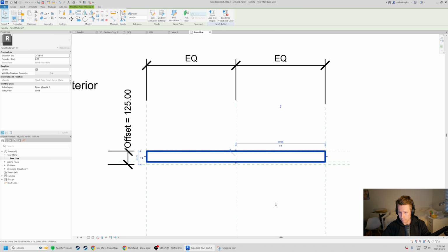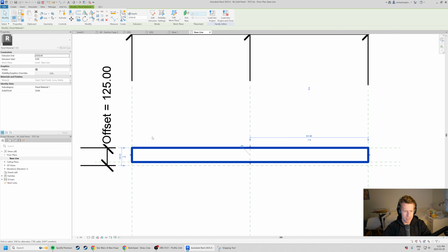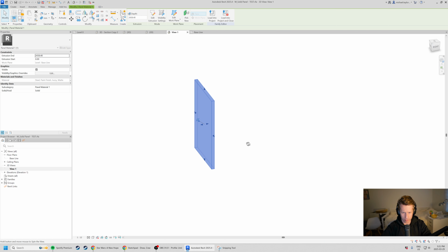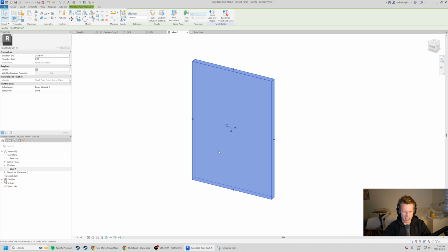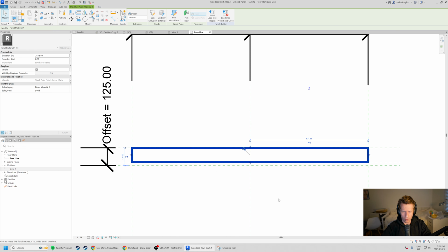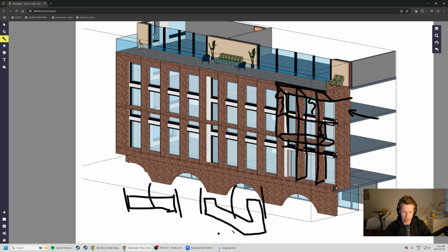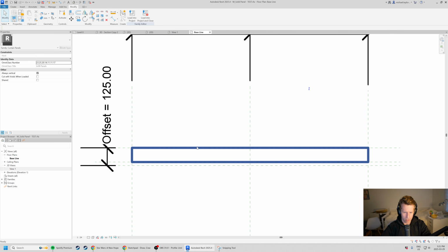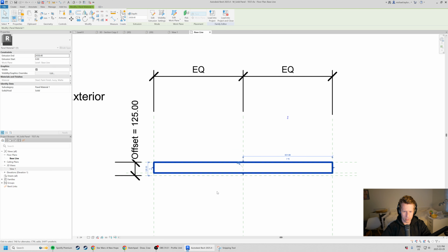252 or maybe 316, when we've got these massing elements, these extrusions living within our family, I'm just going to jump to a 3D view and let's see what we've got here. So this is, remember, our little extrusion. That's all we got, just a little extrusion. In this case, it's a simple rectangular piece. And what we want to do is rather than that rectangle, make it much more like this bad boy right here. So how do we do that? We are going to click on the family, and I'm going to edit the extrusion.